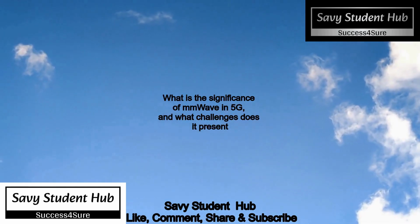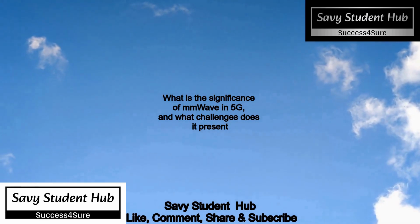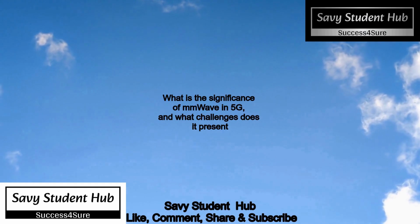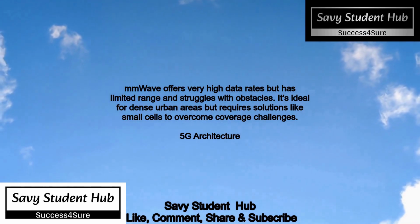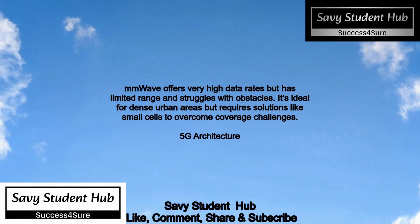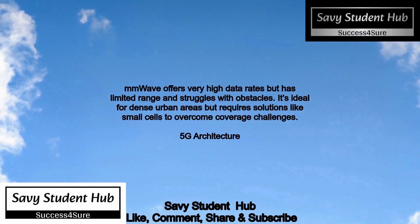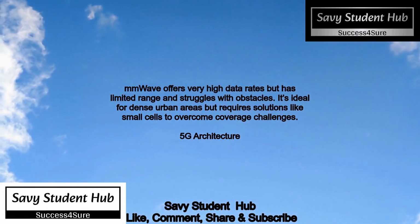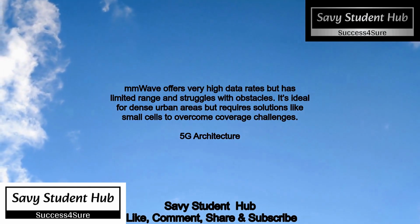What is the significance of mmWave in 5G, and what challenges does it present? mmWave offers very high data rates but has limited range and struggles with obstacles. It's ideal for dense urban areas but requires solutions like small cells to overcome coverage challenges.